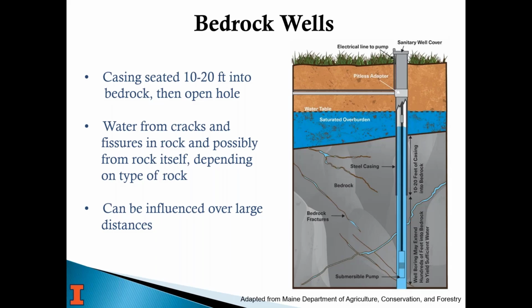I have people call me all the time and say, well, I've got a 400-foot bedrock well, so it's got to be safe. Well, if you look at the log, it may be that there's only 30 feet of casing. So that means the well is open to water anywhere from 30 feet down to 400. And so it doesn't necessarily mean that the depth doesn't matter, casing matters, and especially solid casing.